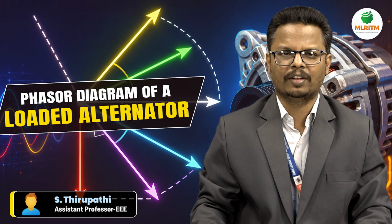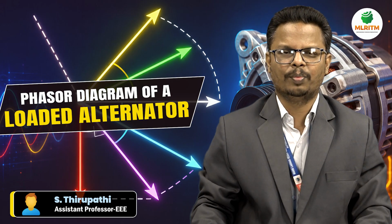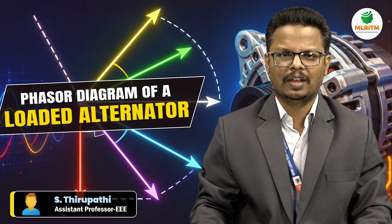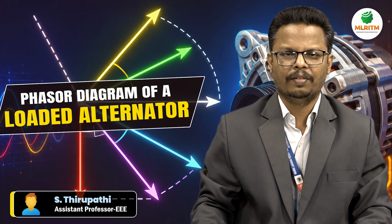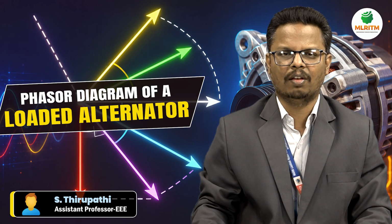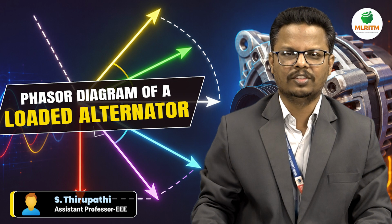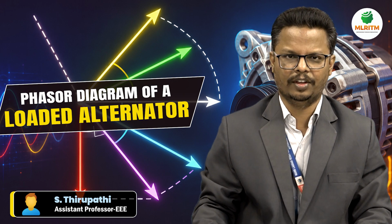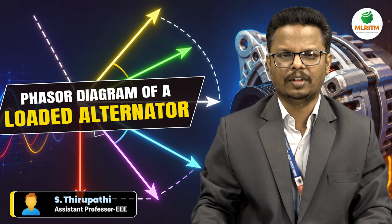For pure inductive loads, the current lags the voltage by an angle of 90 degrees. For a pure capacitor, the current leads the voltage by 90 degrees. If it contains any internal resistance, then there is an angle of φ. So these are the basic concepts of resistor, capacitor and inductor. Now we will discuss the steps to draw the phasor diagram.